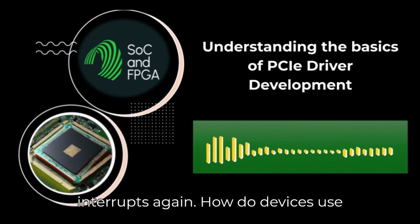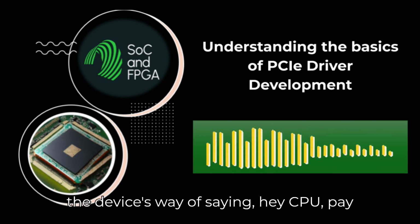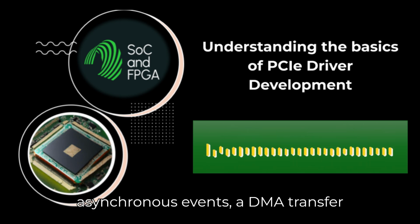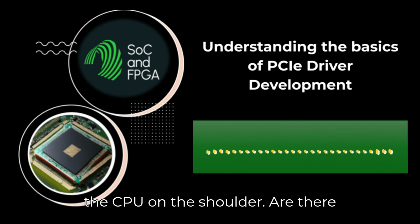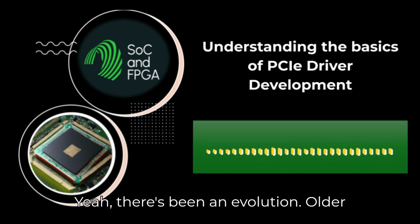You mentioned interrupts again. How do devices use those to signal the CPU? Interrupts are the device's way of saying, hey, CPU, pay attention, something happened. It's for asynchronous events: a DMA transfer finished, new network data arrived, an error occurred. It's the device tapping the CPU on the shoulder. Are there different kinds of interrupts in PCIe? Yeah, there's been an evolution.